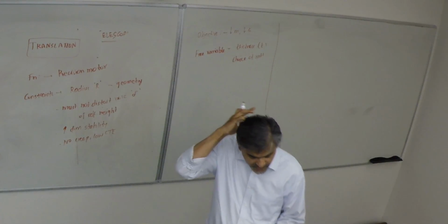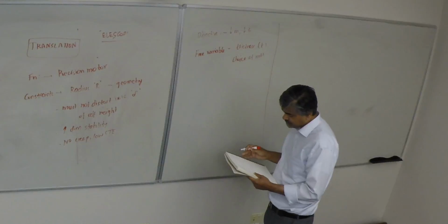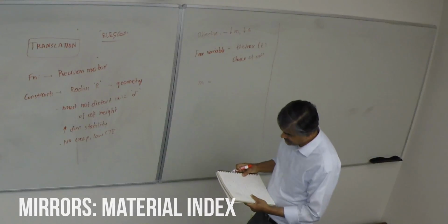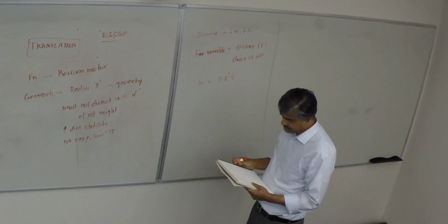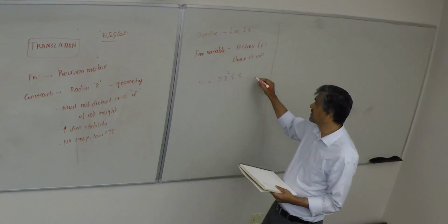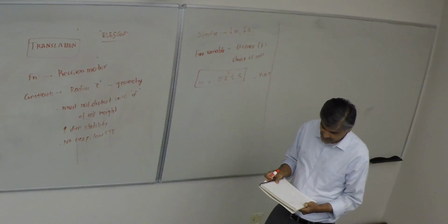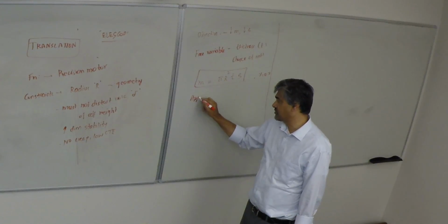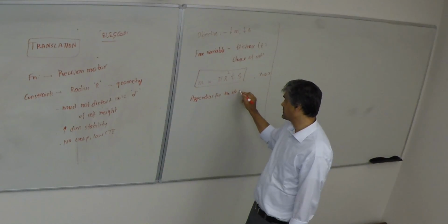So in this, like we have done in previous cases, I'll just lay down the philosophy, I guess. So this being a disk here, we are looking at mass. Therefore the mass in terms of volume should be pi r squared t times rho, because it's area times thickness. Typically we take Poisson's ratio as 0.3 in this case, but that doesn't appear in this term anyway. Then again, like I said, based on the geometry, you have to look up the appendices for the cross-sectional properties for these.